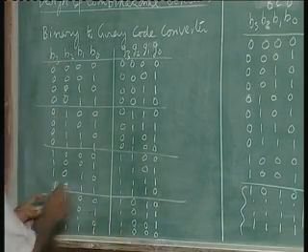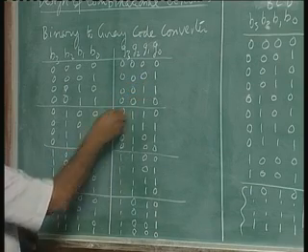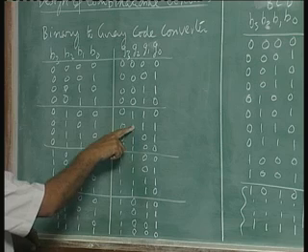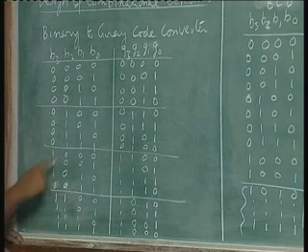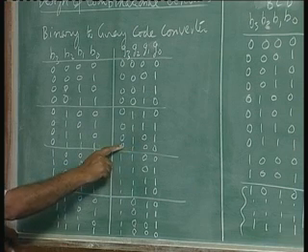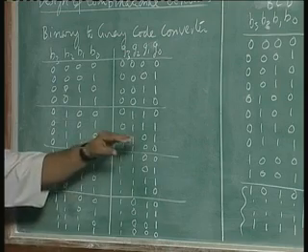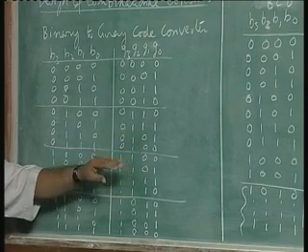You can see now between one number and the next number there is only one position. For example, there is only one change here. You see anything? For example, this 7, here it is 7 to 8, 1, 1, 1 becomes 0, 0, 1, 0, 0, 4 changes. Whereas here is only 1. There is a 1 here, 0 became 1, rest of them. Only one bit has changed from one number to the next number in a gray code.